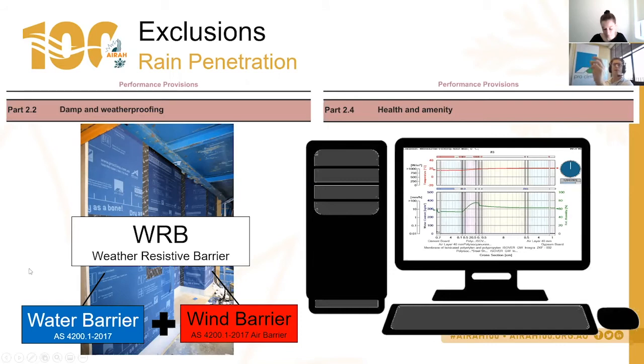So to do that, the computational analysis that DA07 is dealing with is hygrothermal analysis, which generally is a dynamic simulation that requires temperature and humidity inputs and outputs to the model for every hour of the year, but is normally run consecutively for 10 years to work out whether you're going to get moisture accumulation in that system.